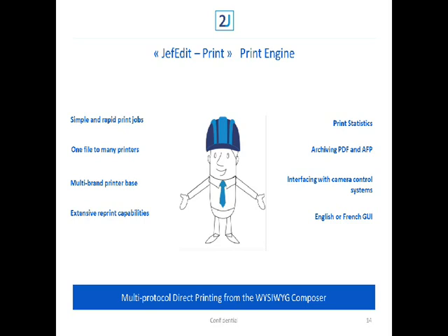2G is also providing a camera control system. Some areas on the page can be captured by cameras. A check is realized in order to ensure integrity and integrality of printing. The control system can be synchronized with the print module in order to start the right control job. The control system then can stop the printing or alert the operator in case of a percentage of errors or in case of a certain number of continuous errors.